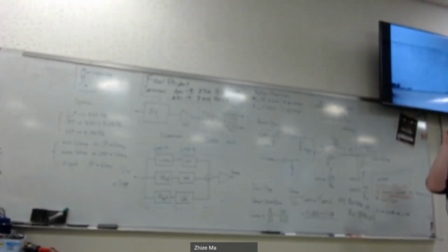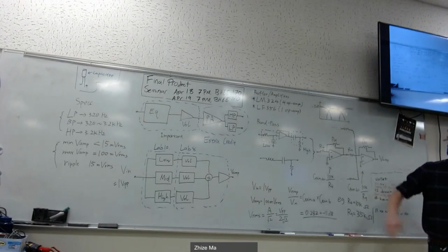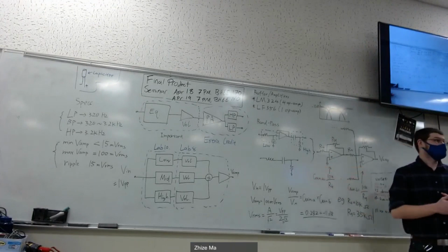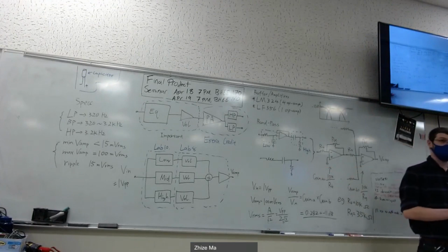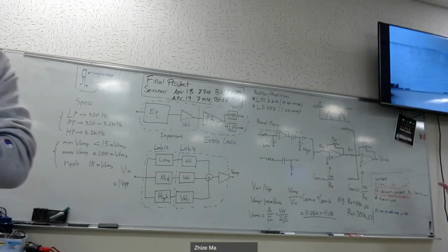If they want a better sound, if they want it to be a little bit more, quote unquote, what you would see in more of an industrial situation or what you would actually see in a product, they can go with the RLC version, using an inductor in series with a capacitor and a resistor. That will get a lot better tone. You'll get a lot more of a deeper sound to that. And if they want to do that, the math does get a little hectic, especially since we don't directly tell them how to calculate resistance based off of the bandwidth.